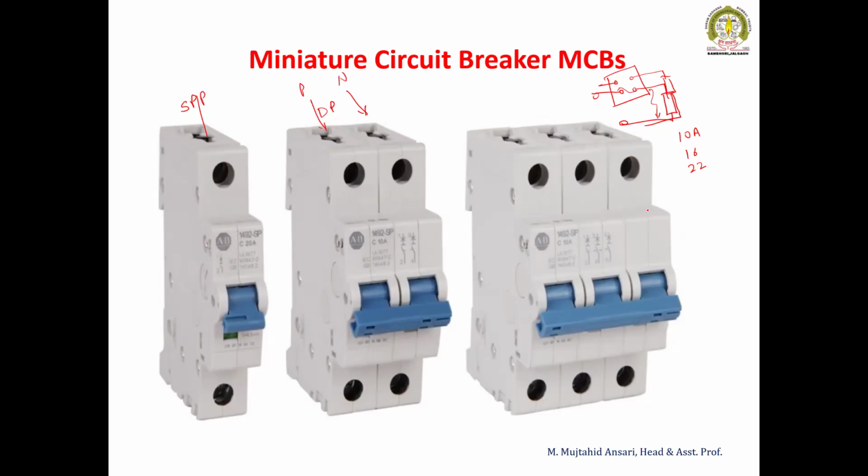It is a three pole MCB which is used for the three phases R, Y, B. There is also a four pole MCB, where we are using one more pole for the neutral. So it is R, Y, B for the three phases and one is neutral.